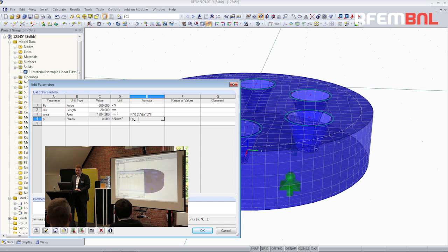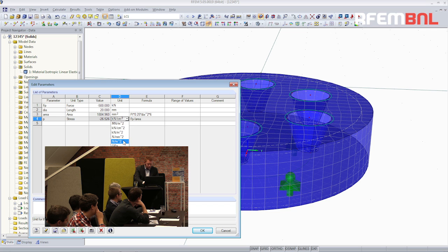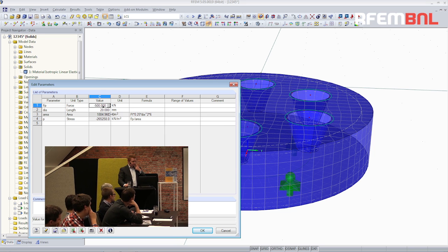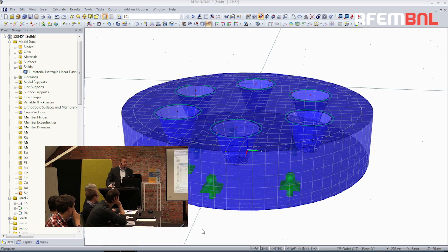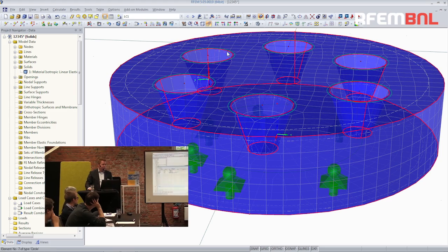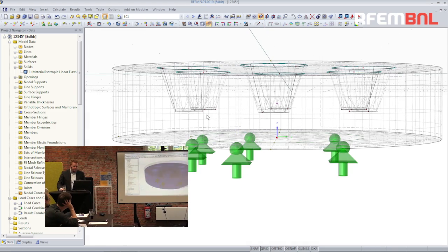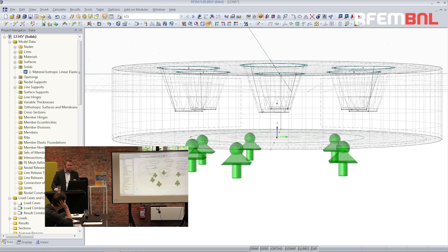I say, okay, this is a stress, like that. And it is FP divided by the area. It's case sensitive, doesn't matter, so like that. And you see that I will work in kilonewtons per square meter. Okay, that is P, the value. It's calculated automatically, derived from this and this. Okay, so turn this off.